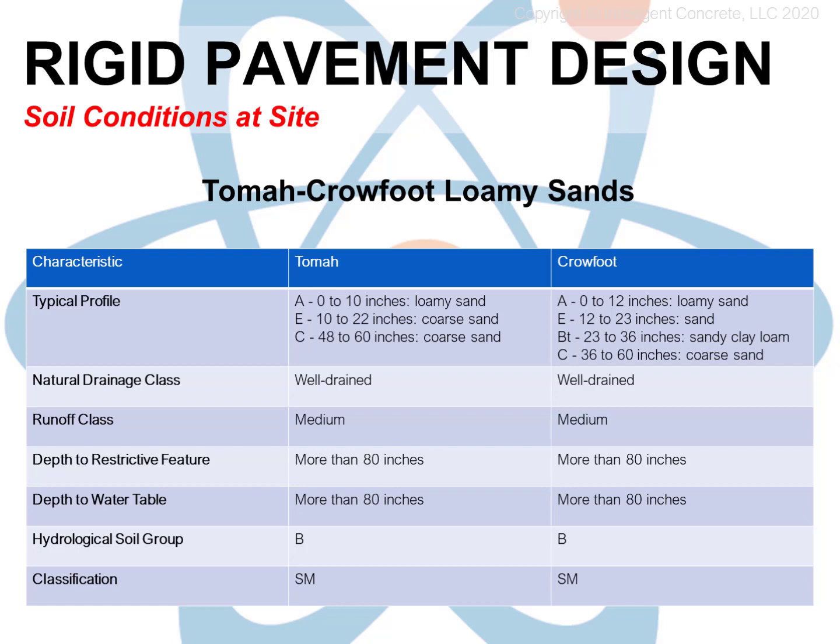Using the Unified Classification System, the designator for gravel is G, sand is S, C is clay, and silt is M. More than 50% of coarse grains would make it a sand or gravel, with silty or clay as modifiers, like silty sand or clay gravel, and so on. More than 50% fine-grained material makes the soil a silt or a clay, with sand and gravel being the modifiers, like a gravelly silt or a sandy clay. We can get really fancy sometimes with a silty, clay, gravelly sand, but we're not going to worry about that today.